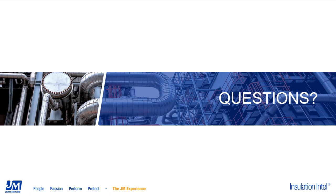That number is used primarily for purposes of radiative heat transfer, which has a minimal influence on overall heat transfer rate, but a very strong influence on jacket or surface insulation system temperature for those situations such as condensation control and personal protection, where the surface temperature of the insulation system is of paramount importance. I'm not positive that answers the question, but I think so.